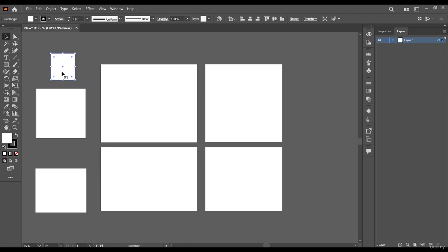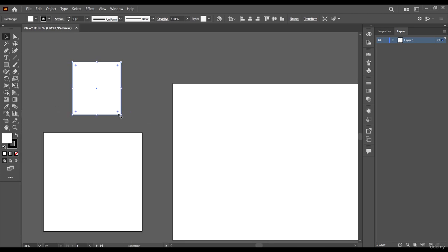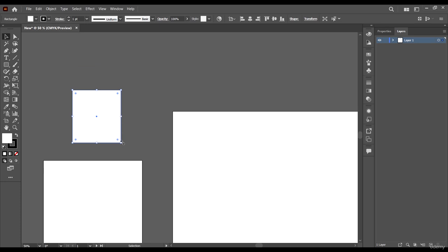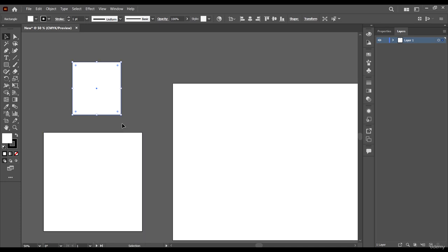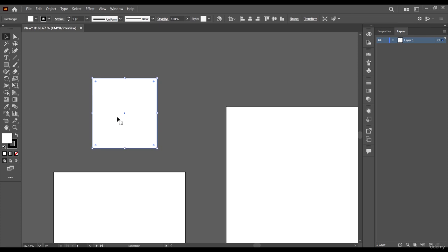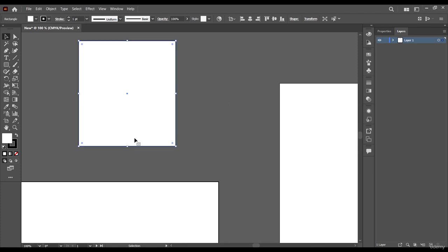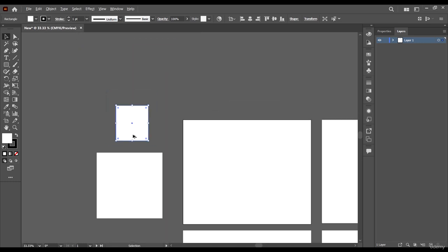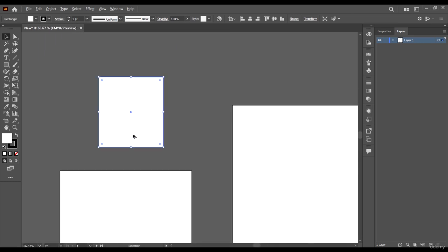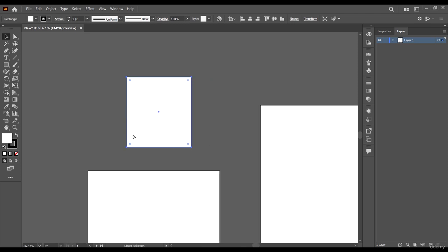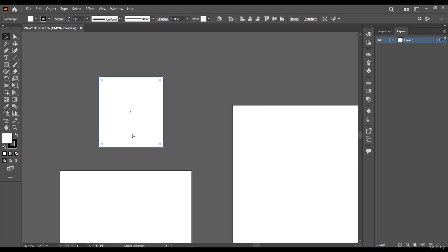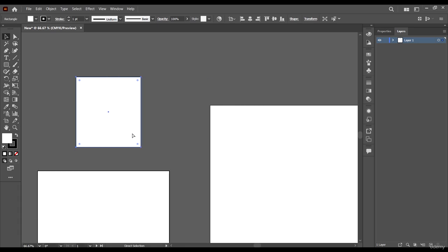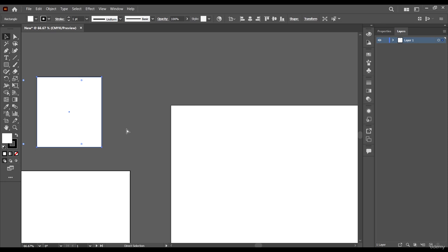Now when we bring our mouse to the edge like this, sorry, I'm zooming in using the mouse wheel and the Alt key. I'm just rolling the mouse wheel while pressing down Alt to zoom in and zoom out. Okay, and to pan left to right, I just hold down the Control key and the mouse wheel, and that's on the PC. If you're on the Mac, you'll be holding down the Command key, right?